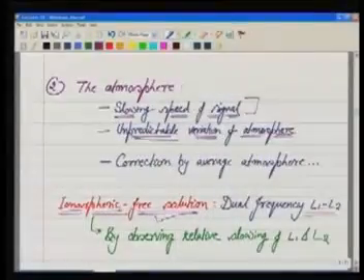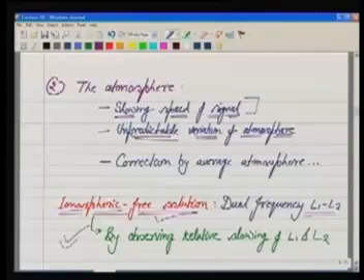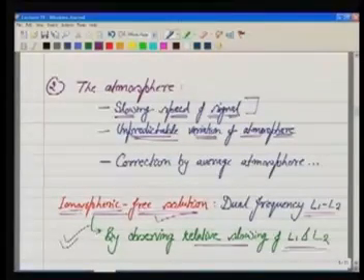But the moment they arrive at the antenna, their times are different. So, by knowing this relative delay in L1 and L2, it is possible that the total delay which is being caused by the ionosphere can be eliminated. So, an ionospheric free solution can be achieved, it is being realized by L1 and L2 by observing their relative slowing.